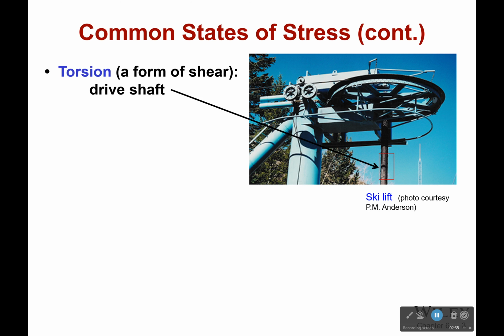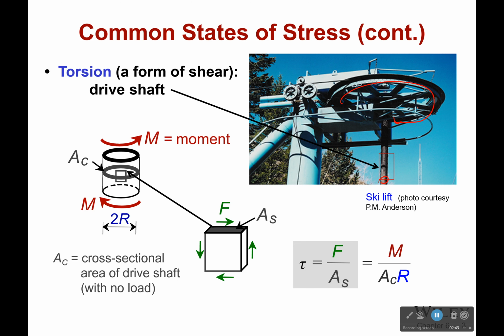Now, another thing that can happen is we can have torsion. So right here we have some motor that's twisting this shaft, and it's allowing everything else to twist around it. And it has to apply a torque to do that. Now, if we're looking at the surface of our rod, what we'll see is that there is some sort of shear force acting at a distance from our midpoint.